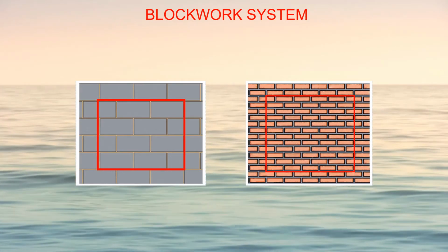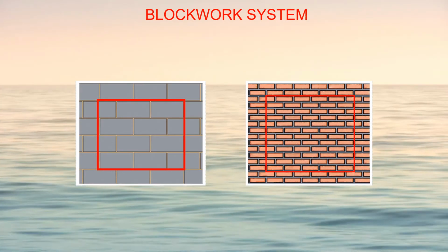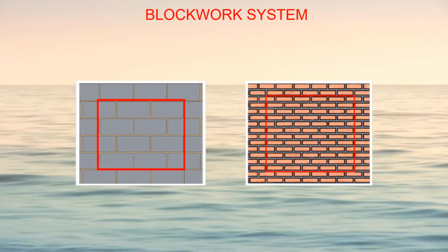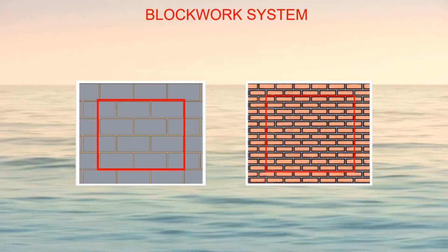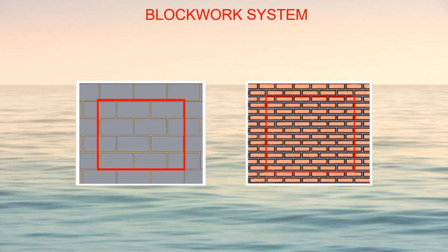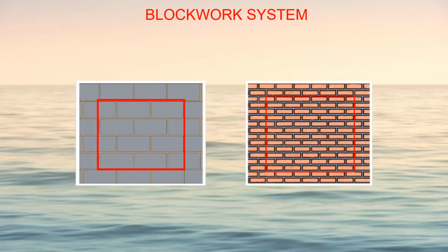Apart from the size of the blocks, the building operations used to erect the walls are the same as brickwork. Basically, there are 10 blocks per square meter as opposed to 60 bricks per square meter.